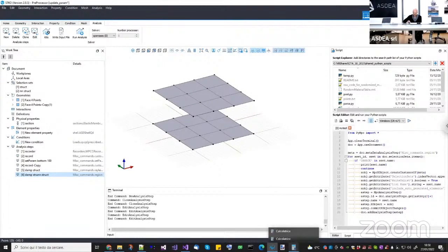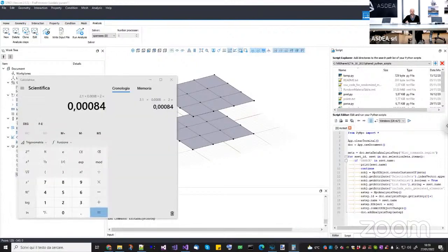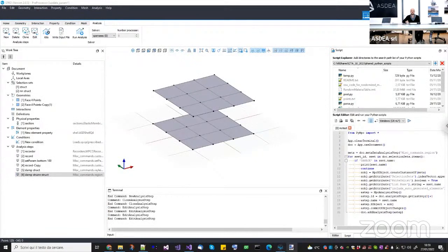So you're talking about the complex eigenvalue problem. Yes. But actually, here you told me that you want to physically model them, and if you model them, you're talking about a complex nonlinear problem. The eigenvalue problem is not your issue. You're not going to do an eigenvalue analysis on a nonlinear model. It's a little bit different. If you want to do an eigenvalue analysis of a model with structural and non-structural components that interact with each other, I'm not experienced in this topic, but of course you cannot do a straightforward eigenvalue analysis using contact elements or any other nonlinear interaction. I was talking about a real nonlinear analysis, okay?